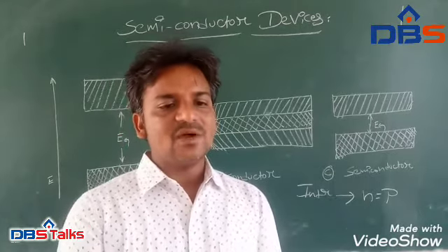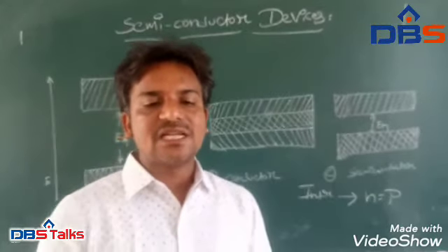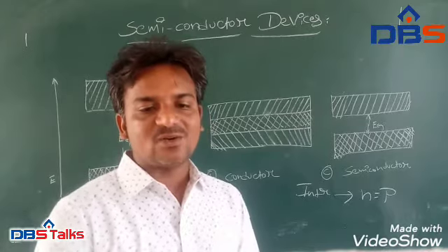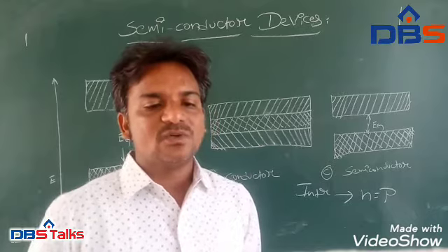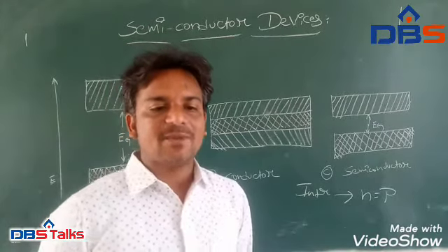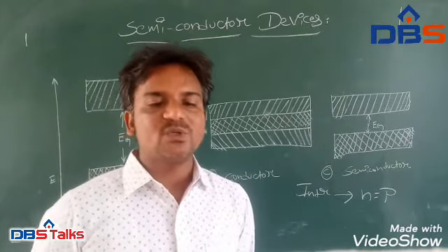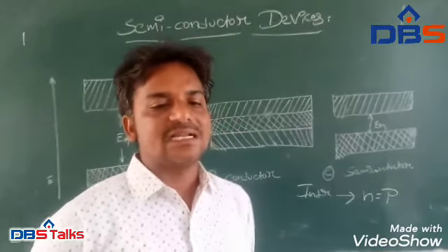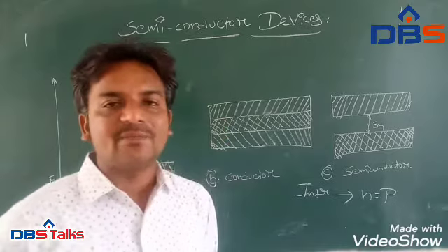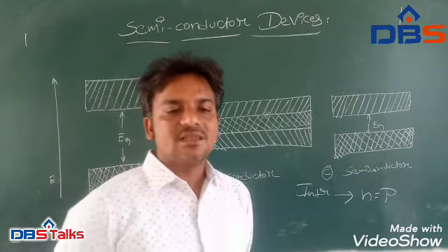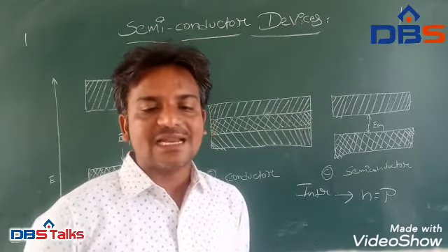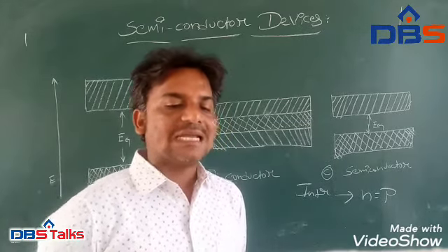A silicon crystal is different from an insulator because at any temperature above absolute zero, there is a finite probability that an electron in the lattice will be lost from its position, leaving behind an electron deficiency called a hole. If a voltage is applied, then both the electron and the hole can contribute to a small current flow. The conductivity of a semiconductor can be modeled in terms of the band theory of solids. The band model suggests that at ordinary temperatures there is a finite possibility that electrons can reach the conduction band and contribute to electrical conduction.